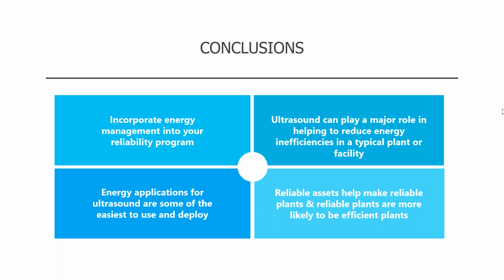And it'll help to improve the overall reliability of your equipment, especially directly related to bearing lubrication. If you're in a plant where you know that you have major issues related to improperly lubricated bearings, that could have a tremendous payback. And not only that, but you can also typically show a 30% reduction in the amount of grease that you're using, because the tendency for time-based lubrication alone is to over-lubricate.